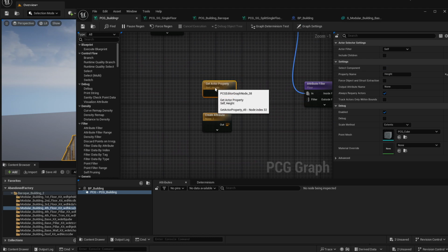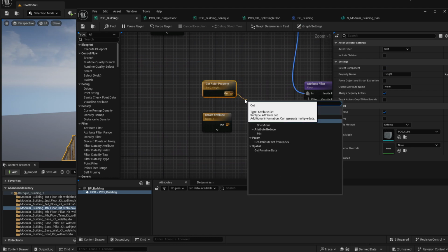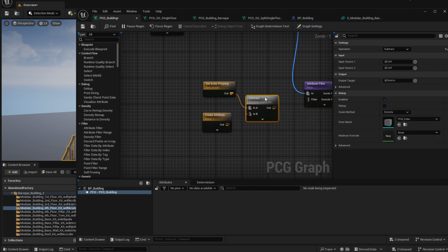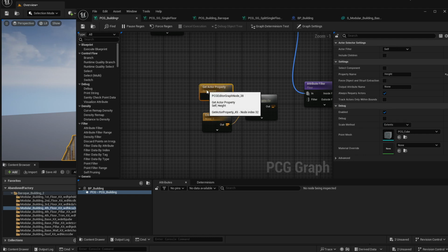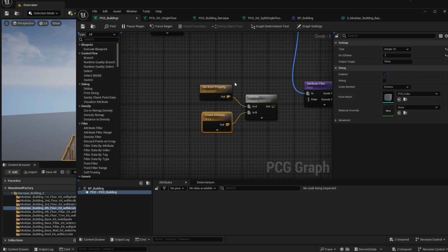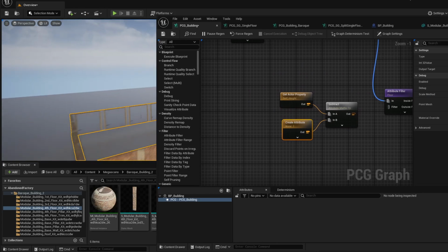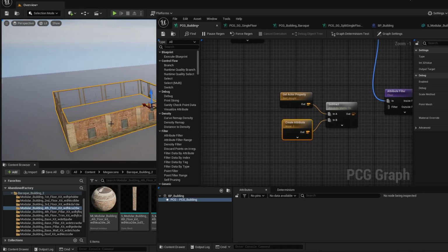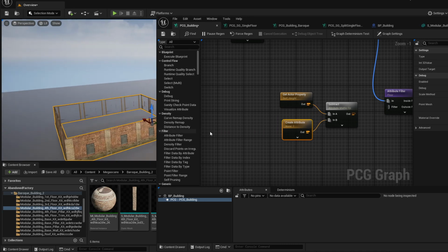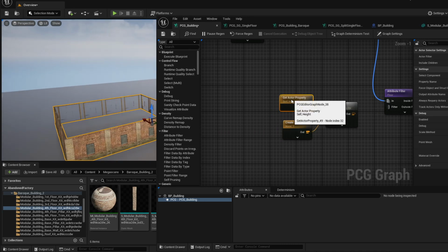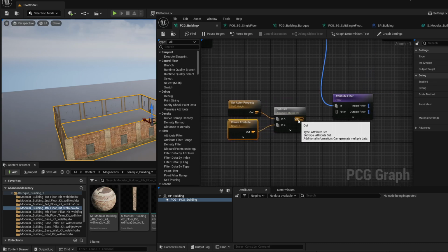Let's paste it here. So let's do a subtract math operation. Make sure that you're creating a math operation and you have this operation set to subtract. So subtract from the height a value of 1, because we are starting the indexes of our floors from 0. So the last floor, when we have a setup with 4 floors, will have an index of 3. So 4 minus 1 will be 3.